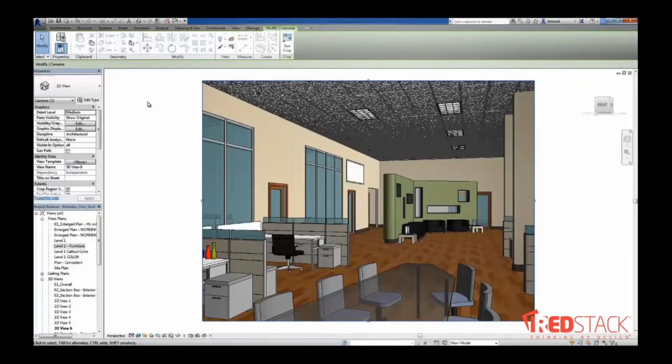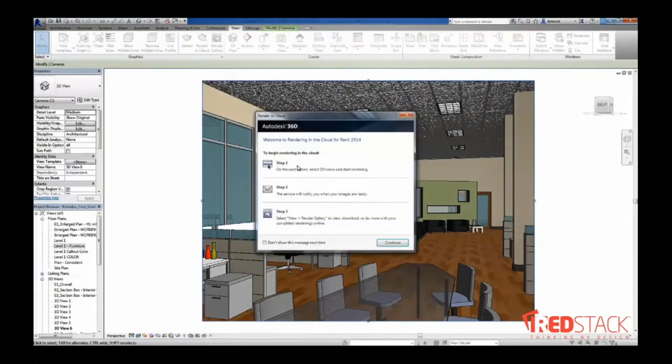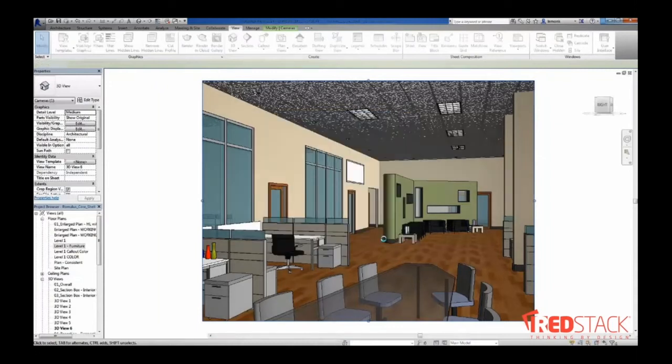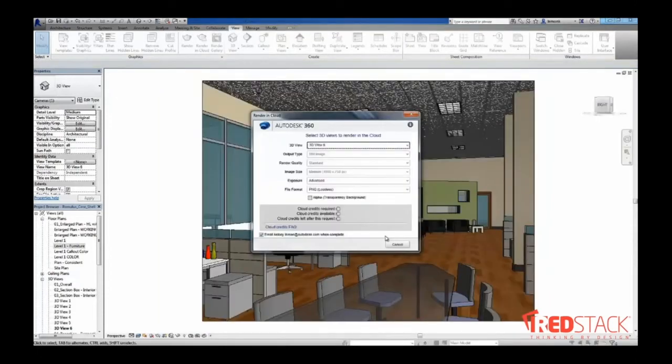In this presentation here, we're going to see Revit render in the cloud. So we've created a viewport from our 3D model, and using cloud rendering services, you can create high definition, high fidelity renderings. In here, you're selecting one view, whether it's a panorama, it could be VR panorama scenes as well. You can select 100 views, push it to the cloud, and have it rendered.